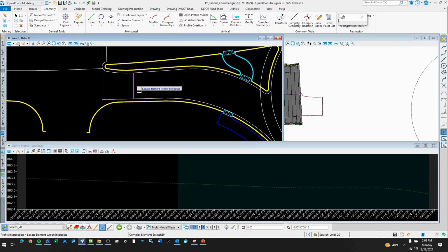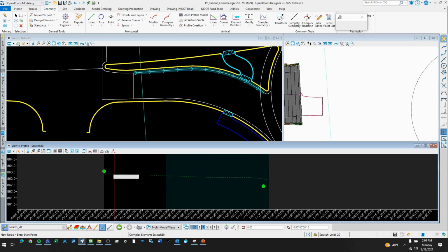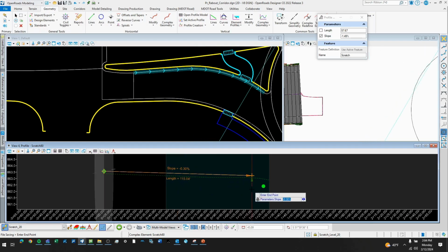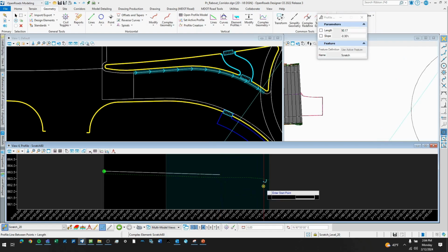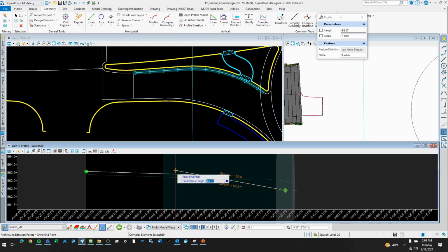I know this intersects, and I know this intersects. So here are 2 points that we need to mesh in together. We want to keep that same slope relative to this, which was that 0.3. And this is where you can change some things if we need to, because this is looking like it's going to end up being a pretty high, pretty steep crest curve potentially.